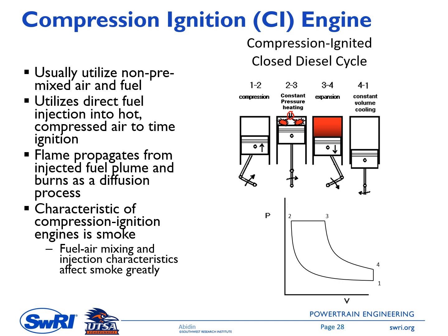The flame propagates from this injected fuel plume and burns as a diffusion process. So we will study this diffusion flame in chapter 10. And then there will be an expansion process. The piston moves toward BDC, doing a power stroke. And then the last one here is the exhaust process. So in this compression ignition engine, we don't have a knocking process.